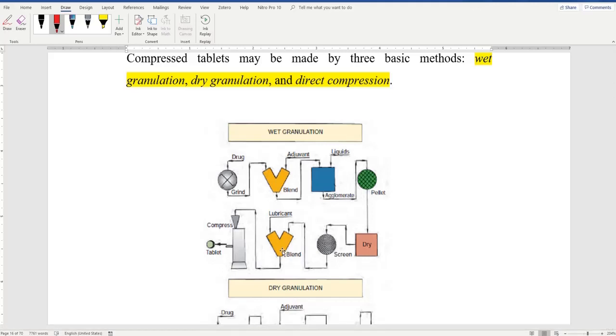And the reason is, if I mix it very well, magnesium stearate will start positioning itself between particles. And when it does that, and I want to do compression, it will prevent granules and particles from sticking to each other, because it is a lubricant and doesn't allow sticking to happen. That's why I only need the lubricant to be on the outside of the formulation.